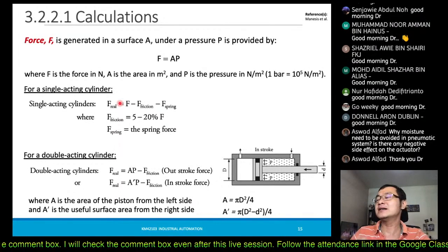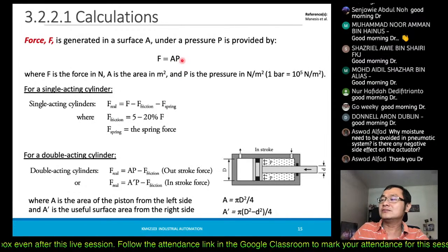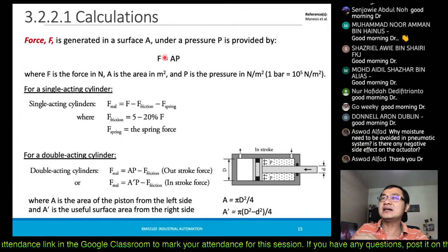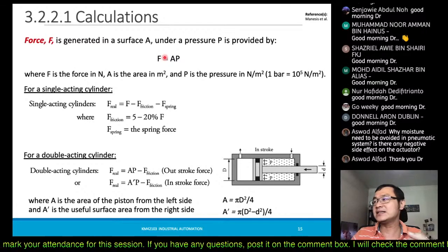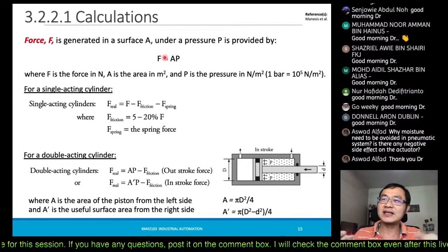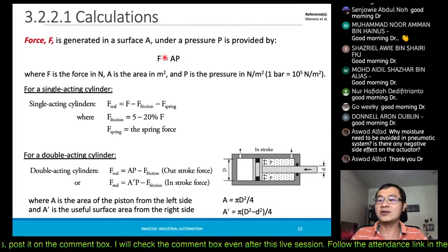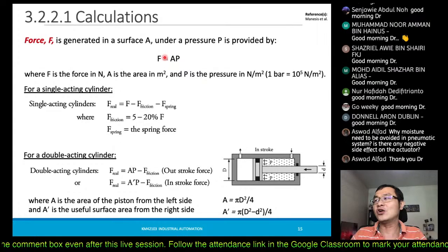You may want a certain pressure to accomplish a certain force, but the construction of the piston or the cylinder itself may not be able to withstand that pressure, because of the size and so on. So that would be the selection part of your pistons.